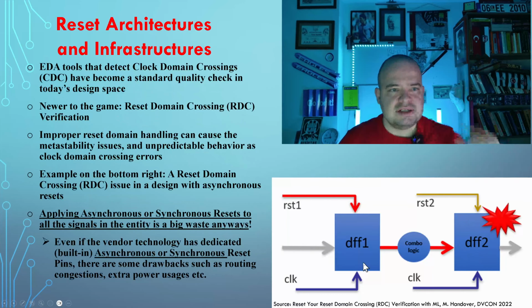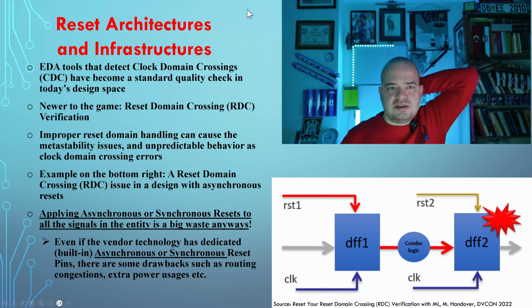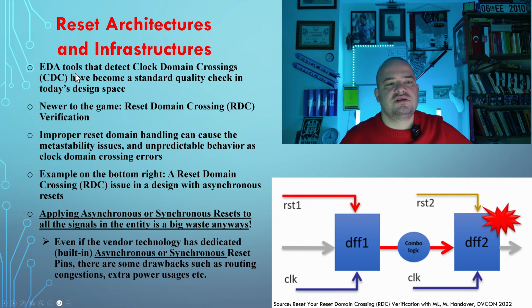Okay, next one was the second slide regarding the reset architectures and infrastructures. EDA tools that detect clock domain crossings, CDCs, have become a standard quality check in today's design space. To be honest, very few companies in the world still use these clock domain crossing tools. You can do some analysis with Quartus and Vivado or other tools as well, but these clock domain crossing tools are really expensive, and they provide much more complicated analysis.